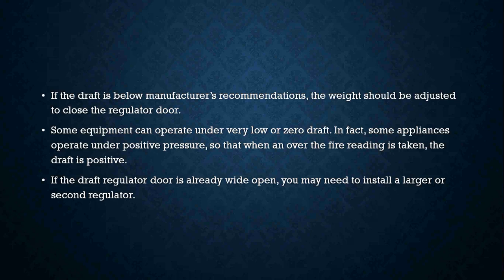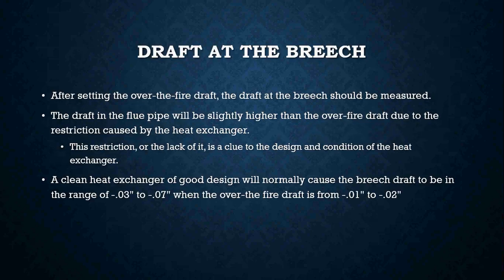Some equipment can operate under very low to zero draft. In fact, some appliances operate under positive pressure, so that when the over-the-fire reading is taken, the draft is actually positive. If the draft regulator door is already wide open, you may need to install a larger or second regulator.